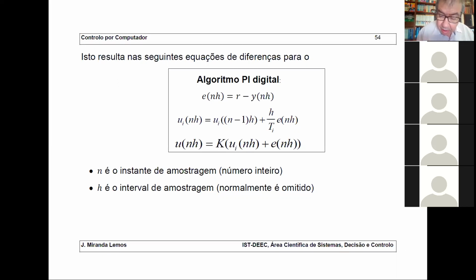You need a very specialized engineer to tune it, and sometimes it does not work because it's so good. That's a story of robustness. So there's no point. If you don't have a significant improvement in performance, use the simplest thing. Always start with a proportional controller, then a PI controller, then a PID, and then move to other things.